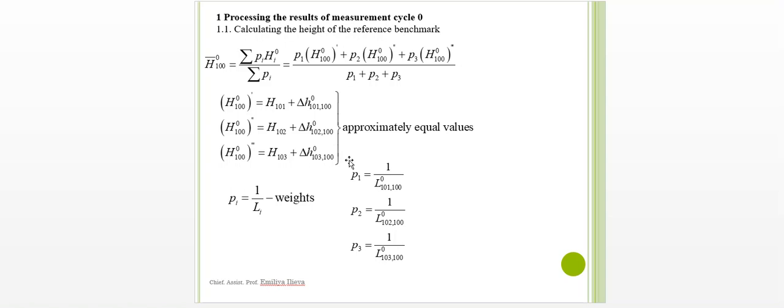Another thing that you must be very careful about is the accuracy. Here the measured differences are with 4 points after the decimal point. So all of your calculations must be with 4 numbers after the decimal point. This is very, very important. And here again the given values for the height of our control point are with 4 points after the decimal point, because these are precise measurements.